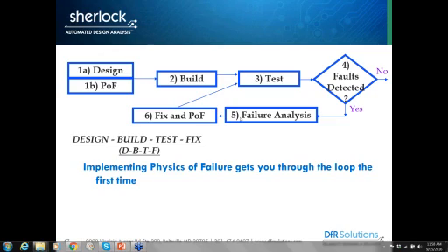Can a user create a design for experiments in Sherlock by defining variables for parameters? Right now, we do not. We do have scripting in Sherlock that we use for testing. We have not exposed that interface to the user. It is very rapid; I can look at different solder thicknesses and how that influences results. I can look at different pad geometries.